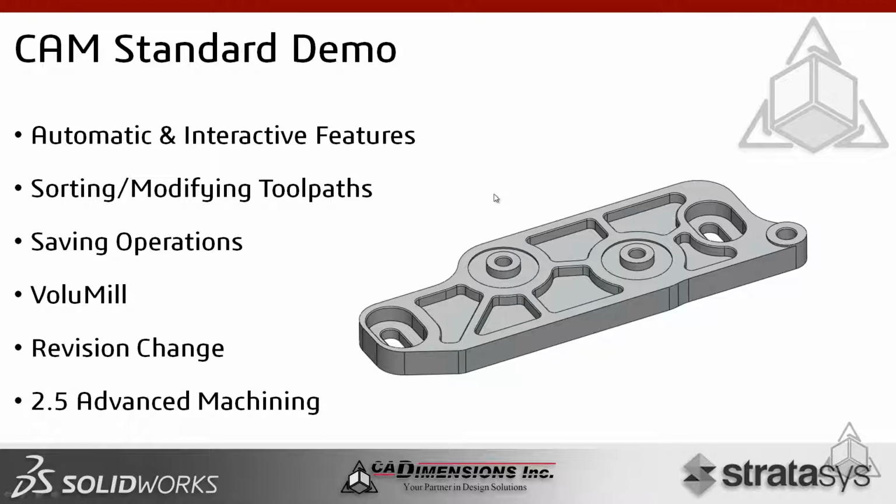We talked about automatic and interactive features. We ran through that automatic feature recognition, but I also did it manually. I just quickly selected a couple faces and that's what generated it. I didn't need to create sketches or create more geometry to do so. I just used the faces that were inside of SolidWorks. Sorting and modifying toolpaths, I did talk about how we would go in and adjust some toolpaths by changing size and changing parameters.